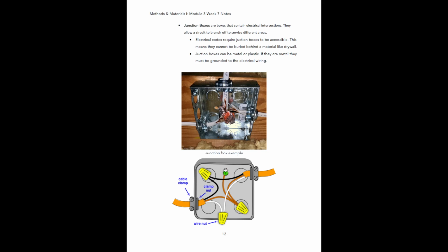So the purpose of this green wire, this ground wire tied to this green screw, is to tie the metal box into that grounding system. Even if a hot wire was exposed and touching that metal surface on the junction box, you wouldn't feel a thing, because the electricity would be tied to this ground wire. It would just go to that green screw, through this ground wire, and then be sent through the electrical system and to the ground through the water line. Okay.